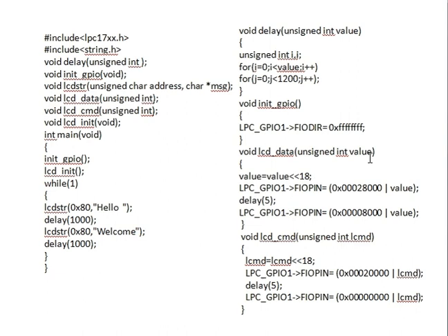I repeat, you have 48, hex value 48 shifted by 18 bits. So bits 18 to 25, the 8 bits of the hex value 48, go and sit in that location, and the remaining bits will be set to 0, and that data is bitwise ORed with 2800.